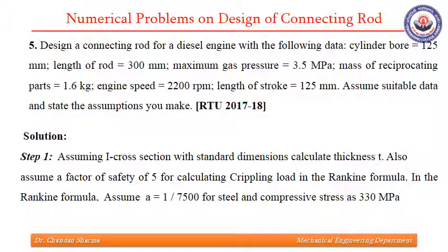That means we are supposed to find the thickness of cross section, then small and big end bearing diameter and length, then big end bolts, big end cap, and also we should check it for the whipping stresses. Here one line has been mentioned that assume suitable data and state the assumptions you make.